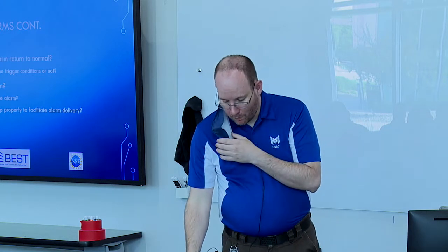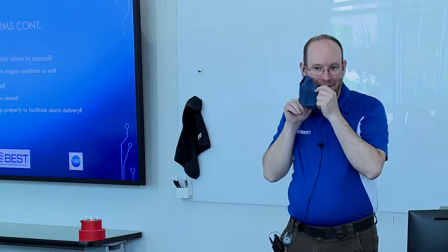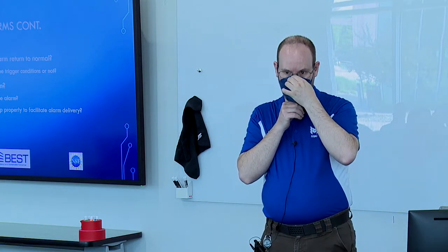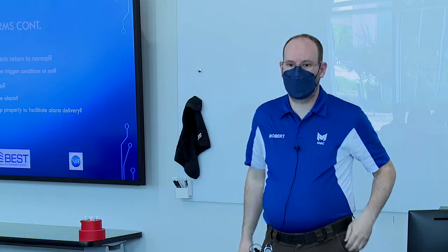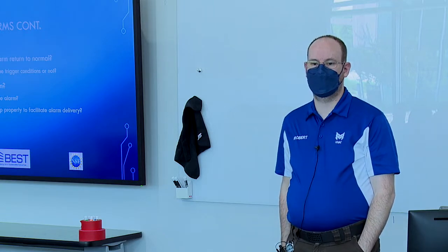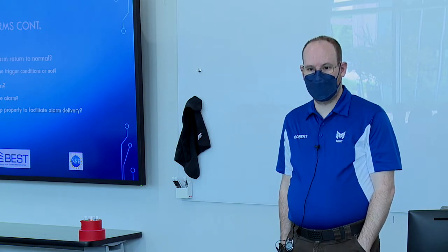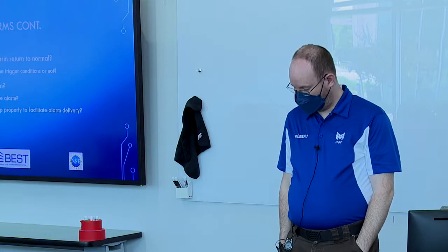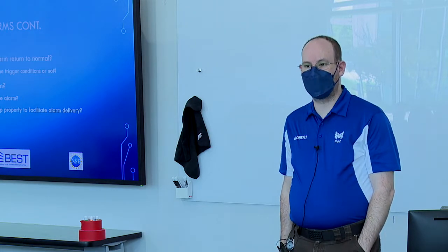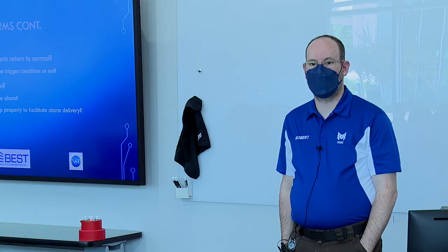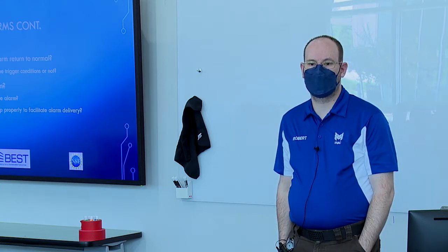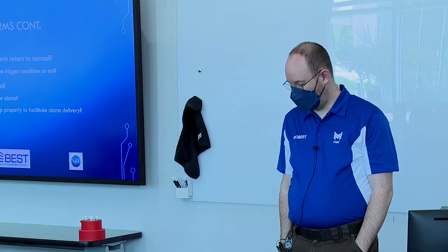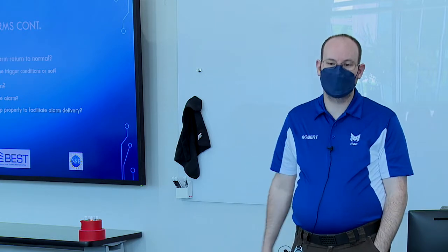Somebody comes in, oh, we're gonna put this control system in and sell you a bill of goods, and that bill of goods falls real short of what they actually need. Yep. And then you've got, on my side of it, I see alarms that are disabled, schedules that are non-existent, buildings running 24/7. Yep. Because on a hot day, they can't cool the building down. So we're gonna turn it on and run it 24/7. Yep. Instead of actually addressing the issue.